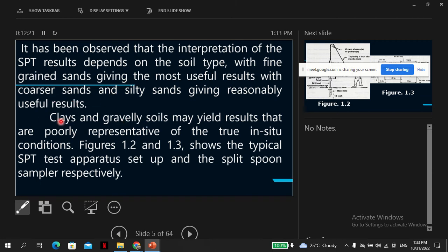Clay is complicated because of pore water pressure, and you remember the issues of clay minerals, montmorillonite. They're quite active, and we even have sensitive clays. You remember, by the sheer fact that you're loading it, you induce a kind of chemical reaction, so the shear strength properties would change drastically. So for these reasons, you can see why there is poor correlation. It doesn't mean that we cannot use this test, because these tests are useful.